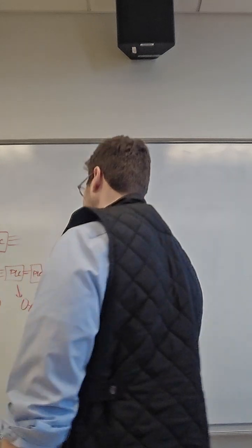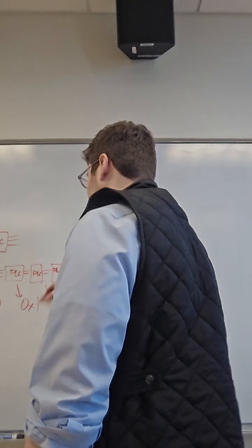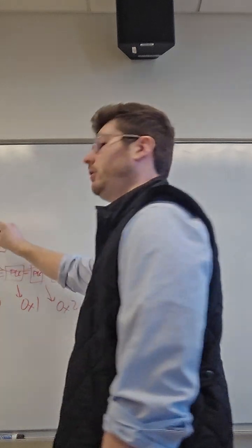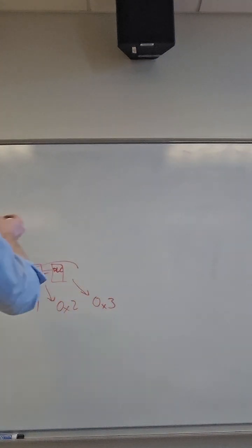So we go, hey, device 0x3, divulge information in register 4. It would go, yes, boss, and it would shuttle up that data. That is serial or RTU.